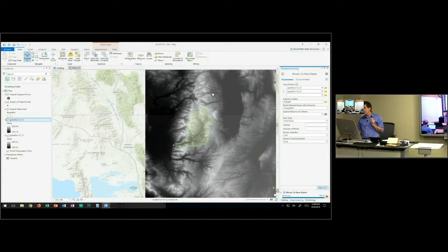The next thing I'll be doing is clipping it out according to the boundary of our basin here. But I actually am going to have to do some coordinate system work first, because I want to work with a consistent projected coordinate system. If you do these raster calculations in geographic coordinates, which is what this data is, you don't end up calculating the slopes correctly, because the horizontal dimension is degrees, the vertical dimension is meters, and the ratio of those two doesn't give you a meaningful slope.